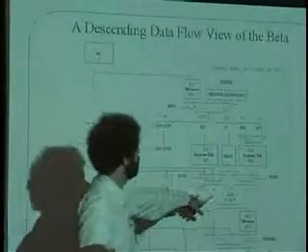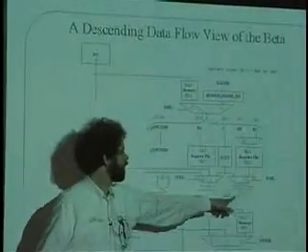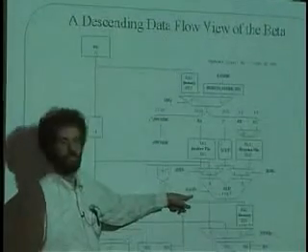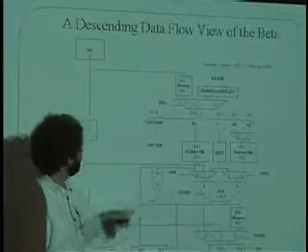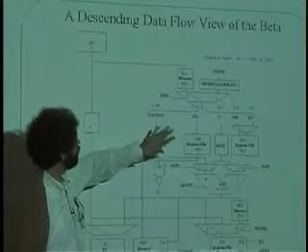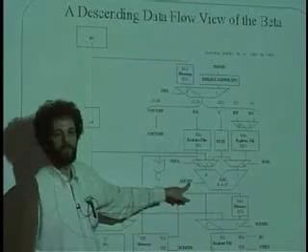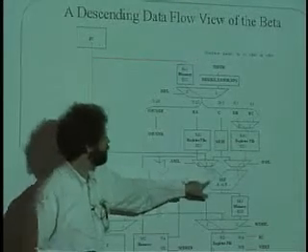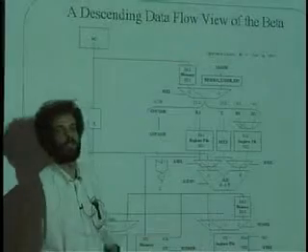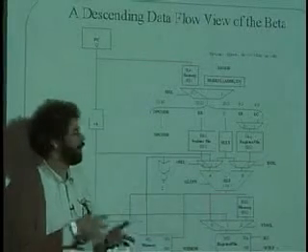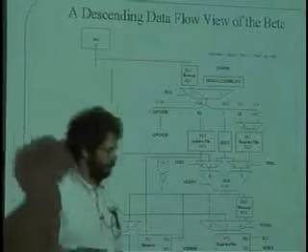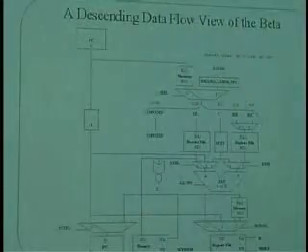We're talking about this thing right over here. It takes the A and the B and takes some sort of an opcode from the instruction stream that is decoded. In other words, there's going to be some logic between this opcode and the command to the ALU saying what function to do, and the ALU is actually going to do the work, and it's going to do things like adding and subtracting, AND, OR, XOR, stuff like that.